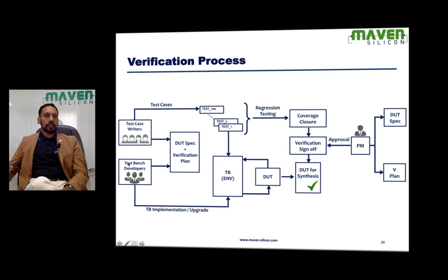Look at here. Both test case writers and Testbench developers, they are going to refer DUT specification and verification plan. Testbench developers take the verification plan and implement the Testbench. It's called reusable verification environment.